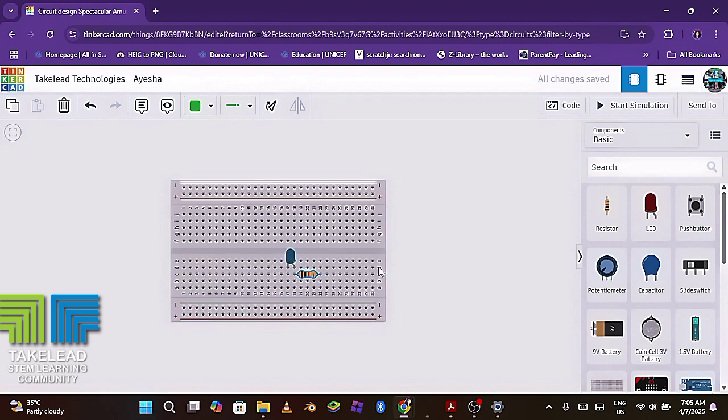On this part, not here, this part takes care of this entire angle from 1 to 30, while this row here, the negative and the positive, takes care of any project or any parts you put within A to E. So we are on A to E. Don't expect to power this area and then expect it to power A to E. No, when you power this area, it will be F to J that would receive the power. So I hope you understand where we are working at.